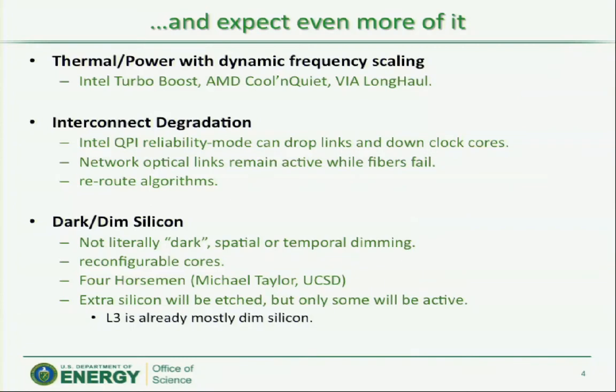So in order to maintain the mean time between failure for the processor, and most processors are sold in the commercial market, where CPU usage is very bursty. There's a human in the loop. You look at your screen for a little while, or you touch a key, or you wait for I/O to happen. Most processors are sold in an environment where usage is bursty, and so they never really bound clocks. But if you run it long enough, eventually the cores are getting downclocked.